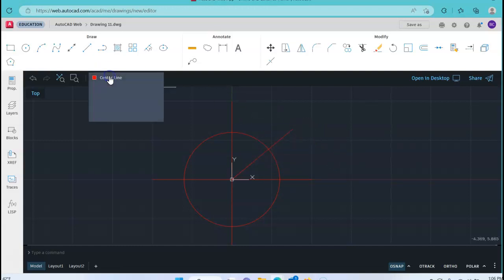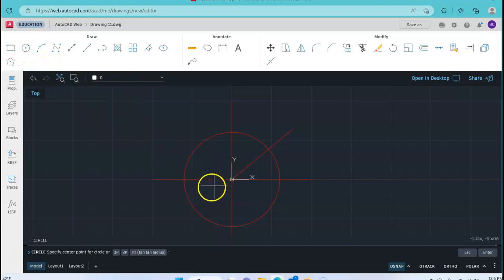So let's go ahead now and go back in, activate the object line layer. We'll go ahead and get some of these circles in. So I'm going to put a circle at center. I'm going to pick the center point up here. Now in this case, again, it is a diameter. So I'm going to go D, enter, 1, enter to place that one.